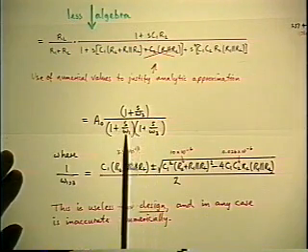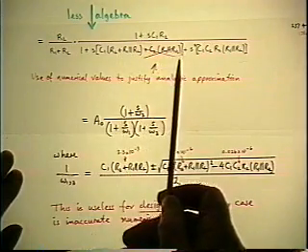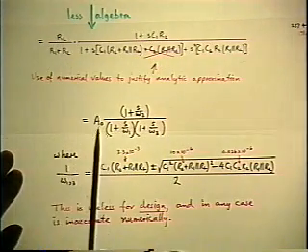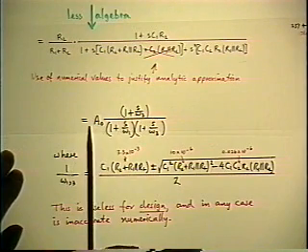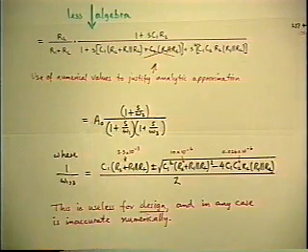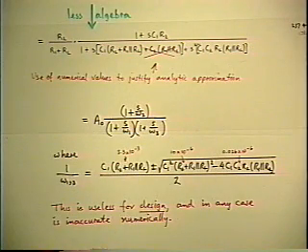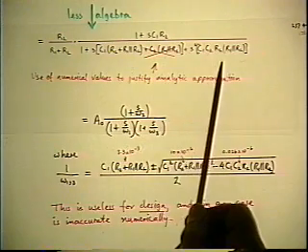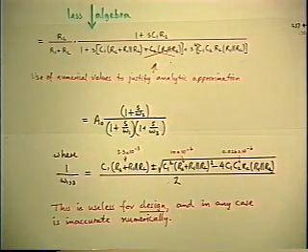So I've designated them omega 1 and omega 3. All of them are in normal format, which means the coefficient in front is identified as the zero frequency flat gain asymptote. So the next thing is, what are the two poles, which of course are the solution of this quadratic equation. Even with the simplification, it remains a quadratic.